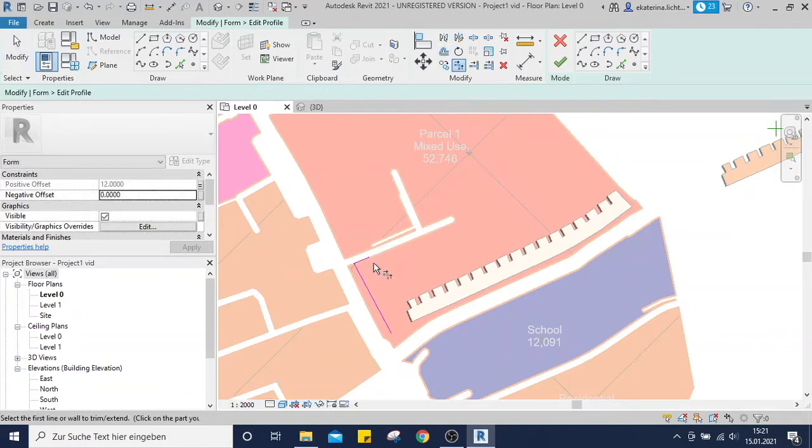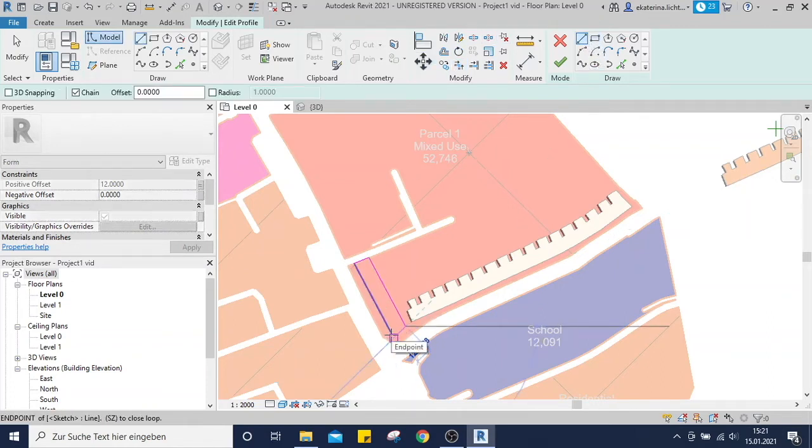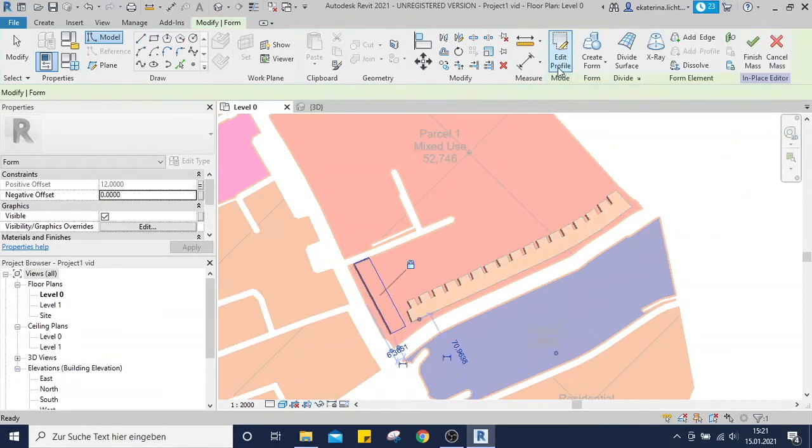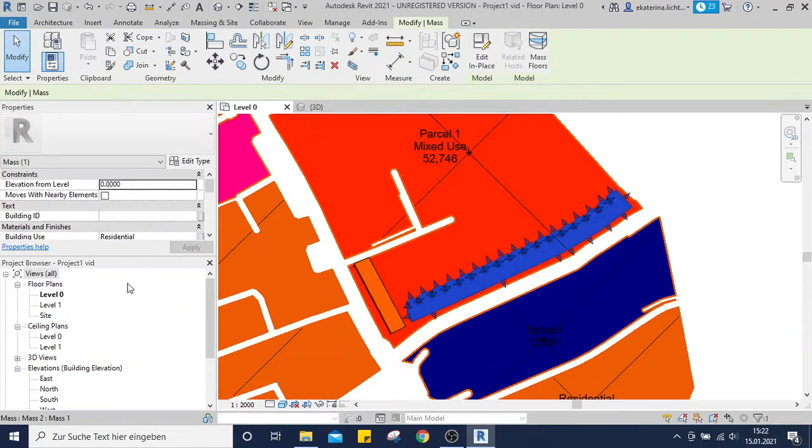And I'm gonna trim this. Oops, trimmed the wrong way around. Trim and connect the lines here. Snap end is SE, and now I'm going to say, yeah, that's okay, and yes, that's okay. Now this one,